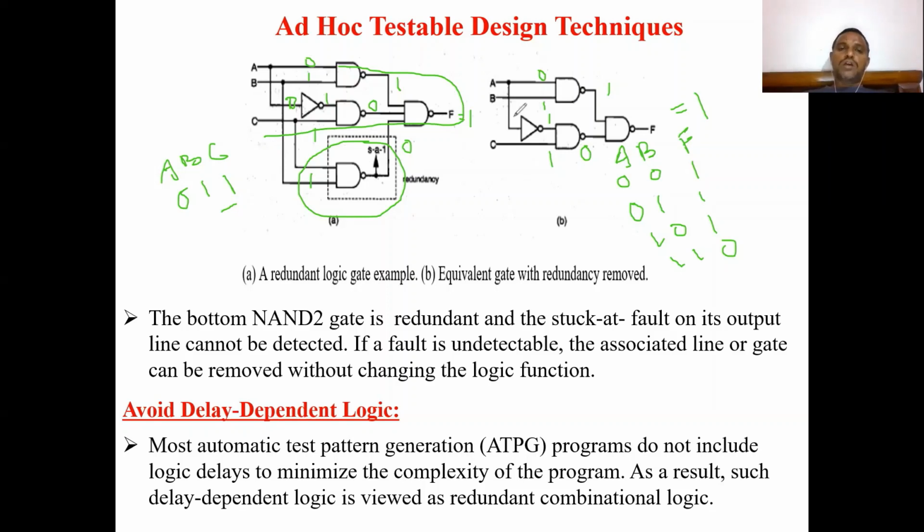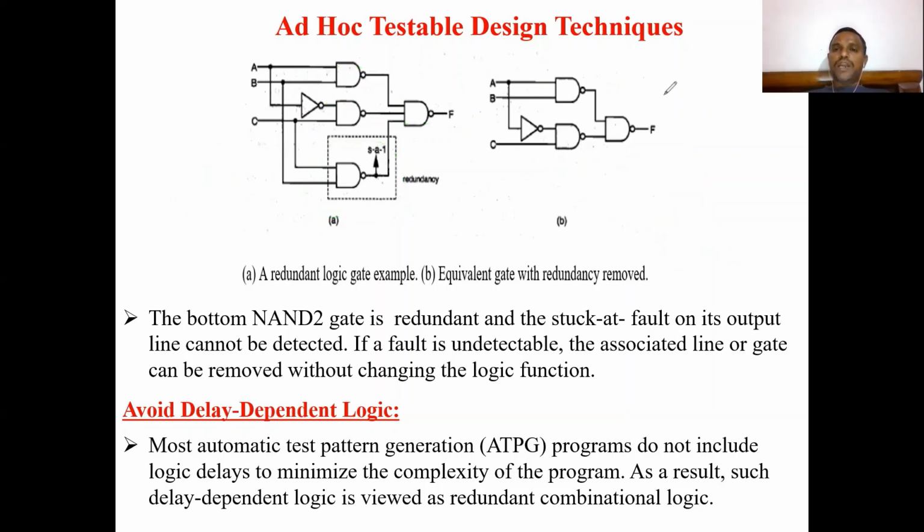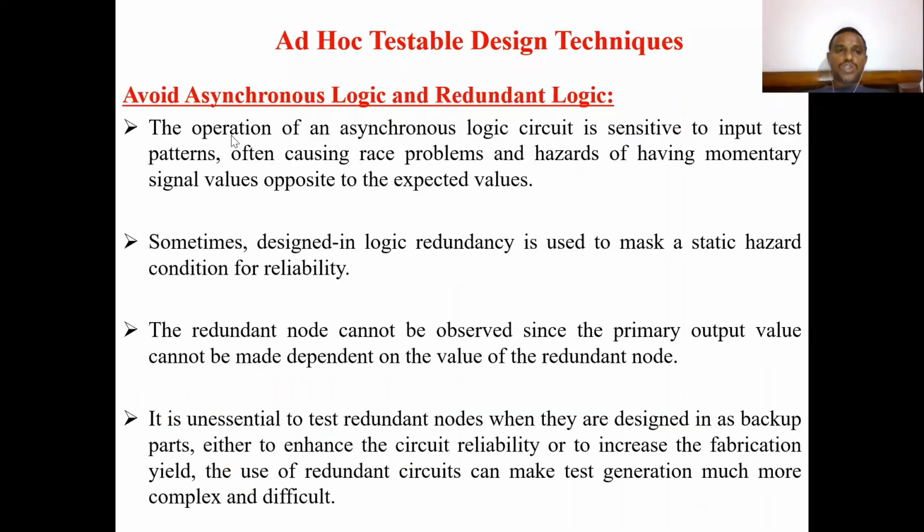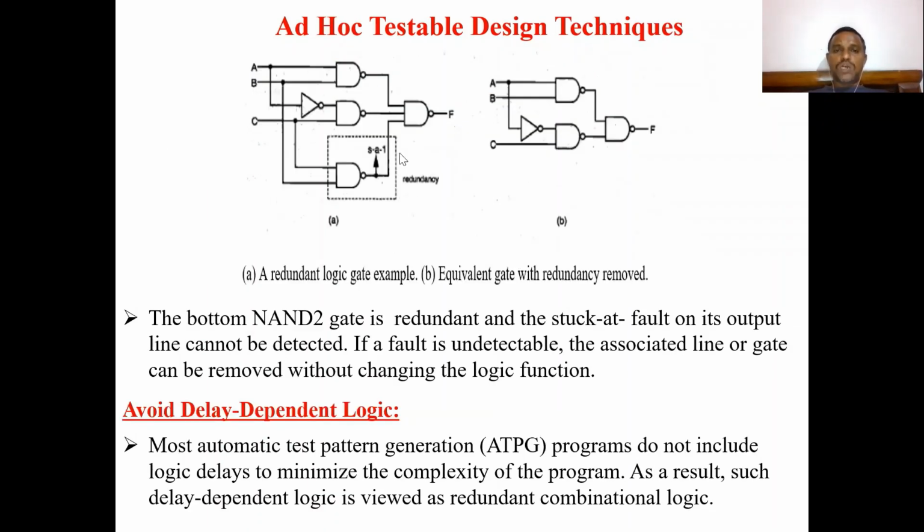That's why it is mandatory to avoid this redundant logic while applying the test vectors or testing. That is one of the ad hoc testing techniques: avoid asynchronous logic and redundant logic.